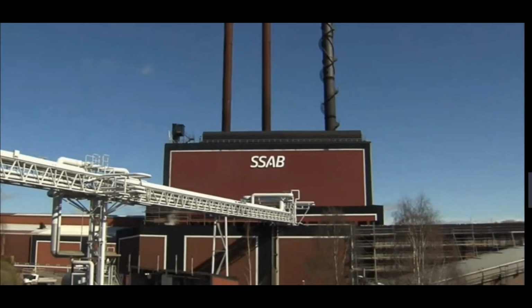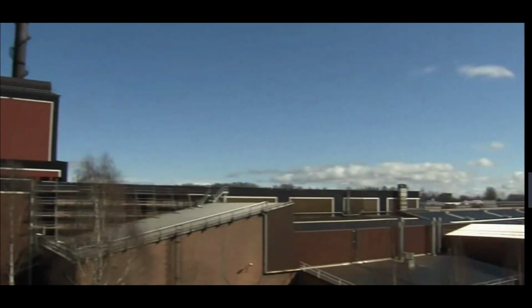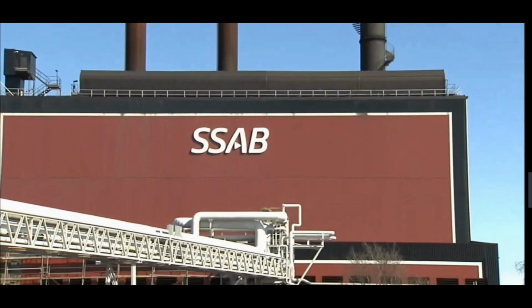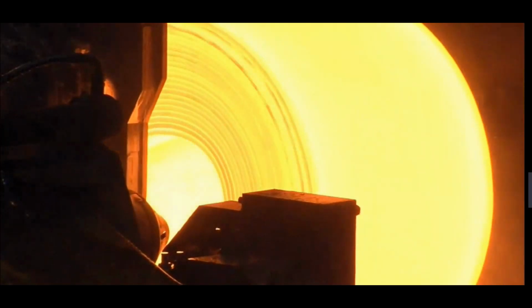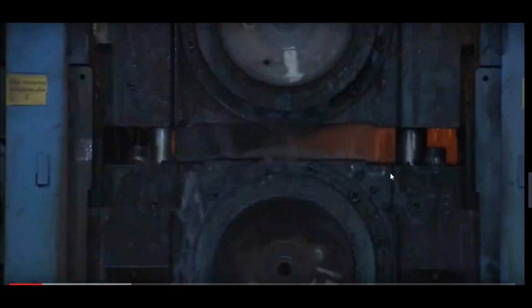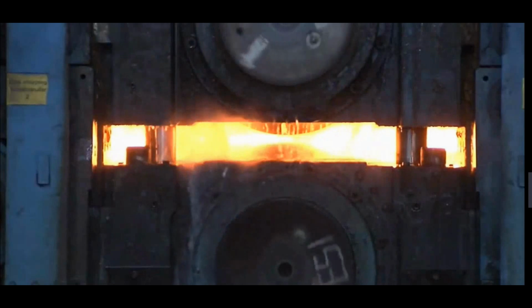This film will give you, as a student, an overview of the processes within a hot rolling mill. The film is made in collaboration with SSAB in Borlänge. Here, the steel material is processed plastically at very high temperatures. Rotating rolls reduce. The material is heated in the reheating furnace, rolled in the roughing mill, coil boxed, rolled in a finishing mill, cooled and coiled.